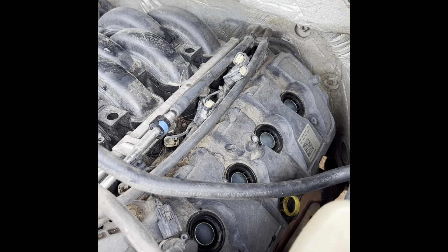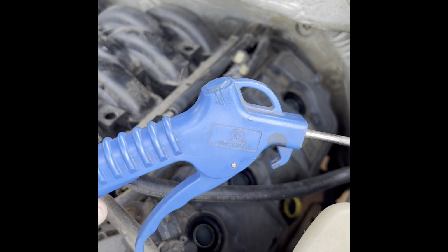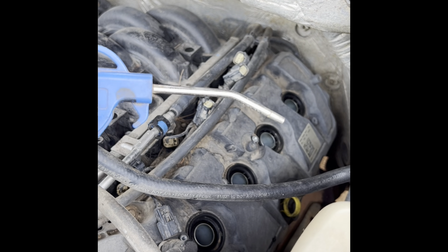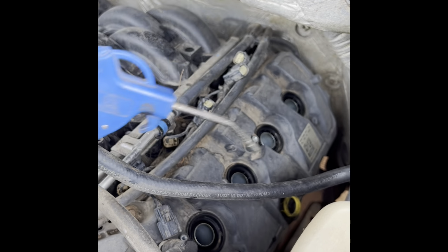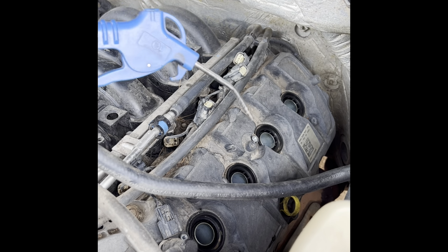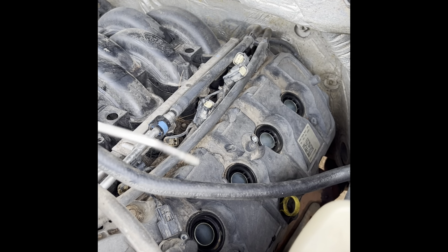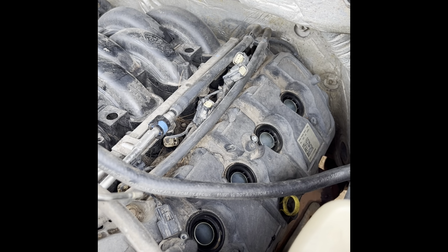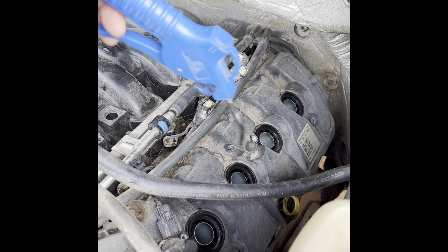Now, a lot of people don't do this next step, but I have learned through the years to do it, because there's stuff that can get down in them. Little dirt and sand and grit can get down in them holes. So I take a blower and blow them out before I remove the spark plugs completely. Just make sure you get all the grit out. You don't want that down inside your engine. Just like sandpaper inside your engine. Hold your ears.